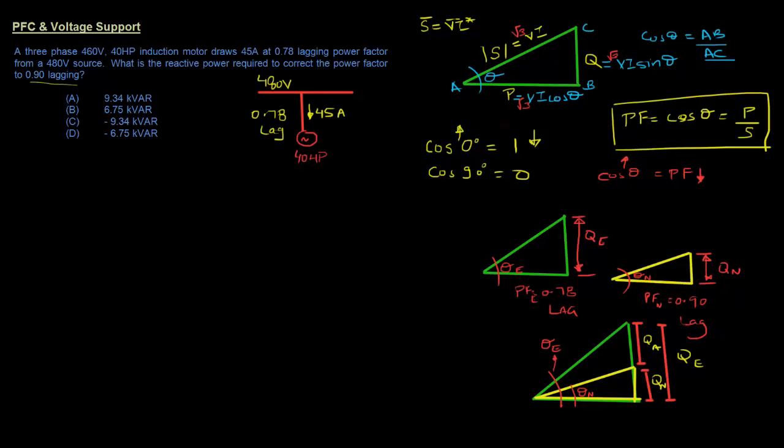So what's happening right now? It's an induction motor, it's a lagging power factor. So we have Q existing being absorbed. Even Q new is 0.90 lagging. It's a lot less, but it's still being absorbed by the system.